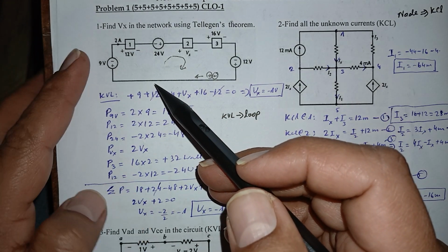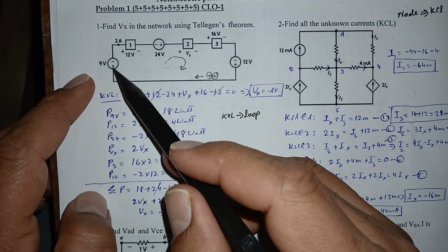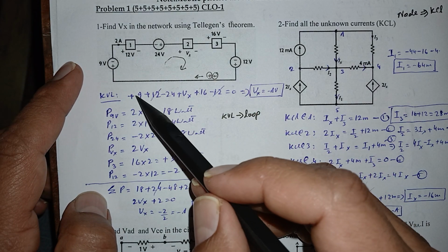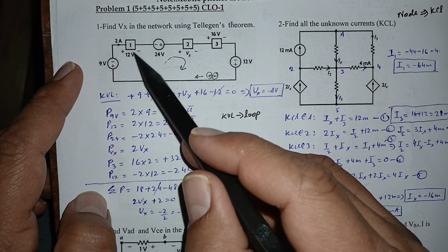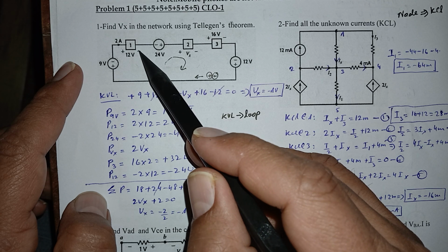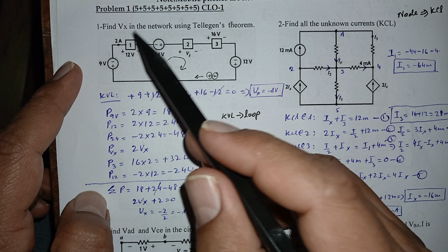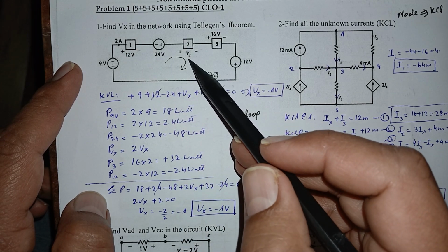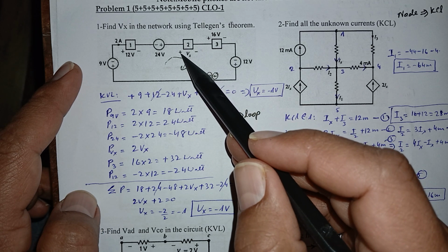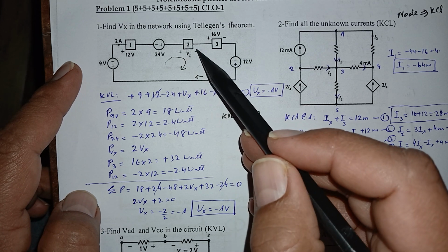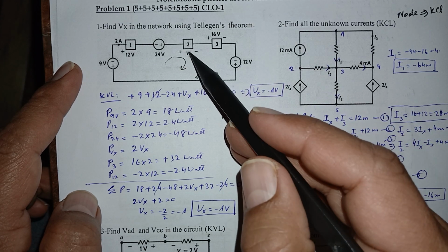So that was the logic, and now I'll discuss the shortcut method. The shortcut method is that if this positive charge hits a positive terminal, I'll write positive here. That means we have to know the polarity of the element. If we don't know the polarity of the element, we cannot write the KVL, so we have to assume. It doesn't matter. For example, for Vx, we don't know the voltage across this element 2, so we can arbitrarily assume this is positive, this is negative. The other choice would be this is negative and this is positive, so it doesn't matter.